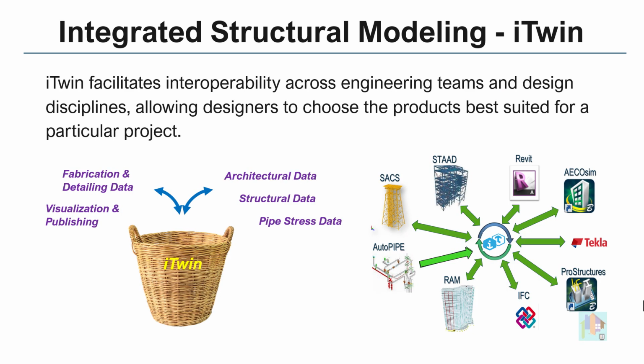There is another way to create a model in RAM Structural. It supports iTwin service. iTwin is a data transfer technology using which we can interchange filtered data between different products. It's like a common basket where anyone can store any information: structural, architectural, piping or generic data, and access filtered data from other products. Most of our products, including STAAD.Pro and RAM Structural, have this facility. A few non-Bentley products like Revit or Tekla also support data interchange using iTwin file.